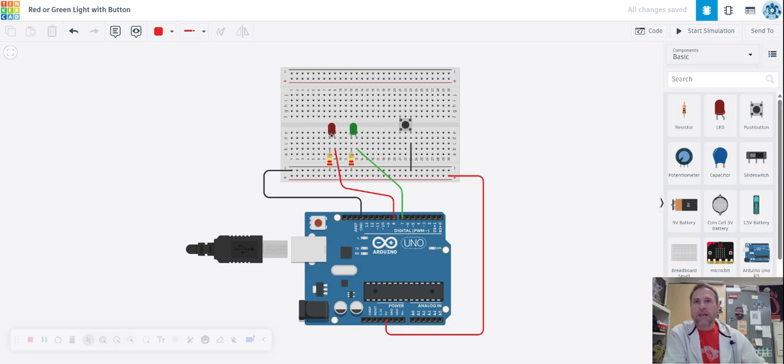It will flow through the LED light. It'll come back out of the cathode, through the resistor, through the black wire here, back to the ground, and once again, this circle has been completed. This pathway has been completed. So the only pathway that has not been completed yet is the pathway to my button. So let's do that right now.